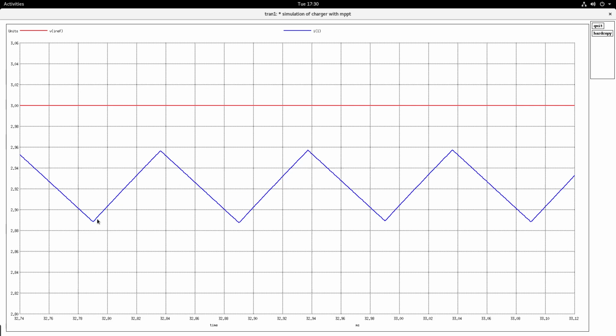Now you see that the inductor current is not reaching up to IL ref. The reason is that we have a slope compensated modified reference which is falling down from the IL ref value, and when it is falling down from the IL ref value, the inductor current will cross it somewhere lesser than the IL ref value and change state, and then start into the downslope mode.